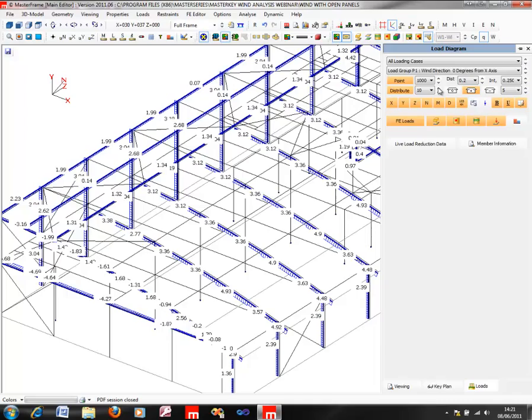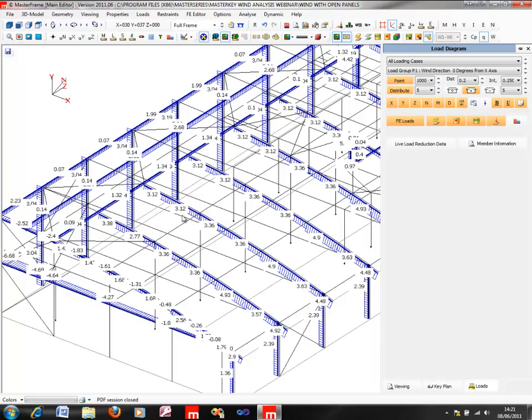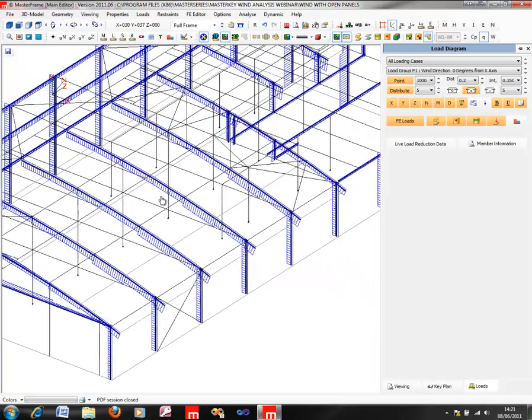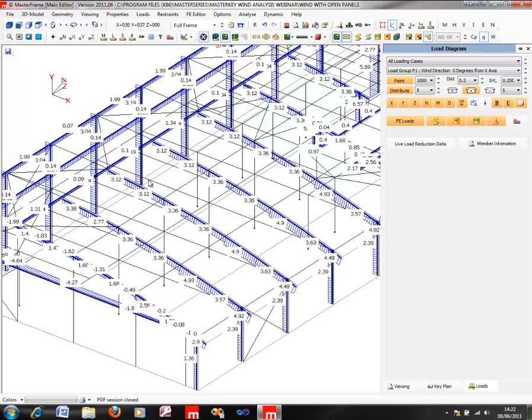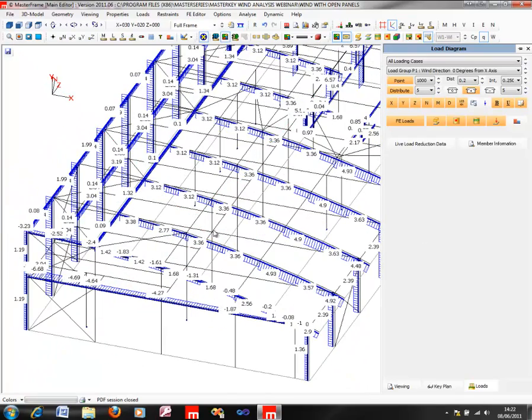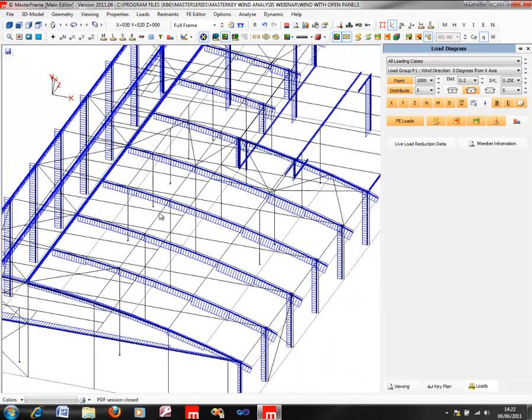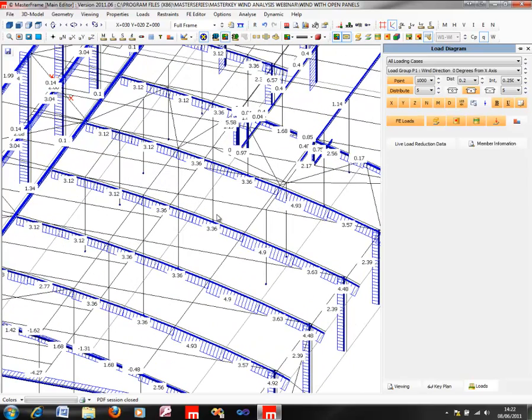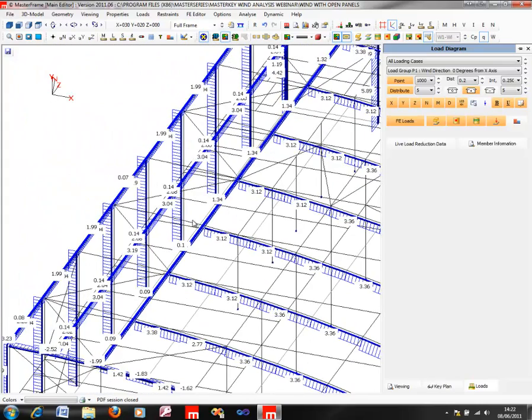and let's change the scale of the distributed loads here, and we can see what we have here. We simply have obviously one-way spanning in this direction, which maybe isn't what we want. We probably want one-way spanning in the other direction, parallel with the x-axis, but that's what was set up here, and we can see everything coming through there on that basis. So we can see the actual kilonewton per meter value coming into play there, and we can obviously easily validate and verify that that is the sort of figure that we would expect there.